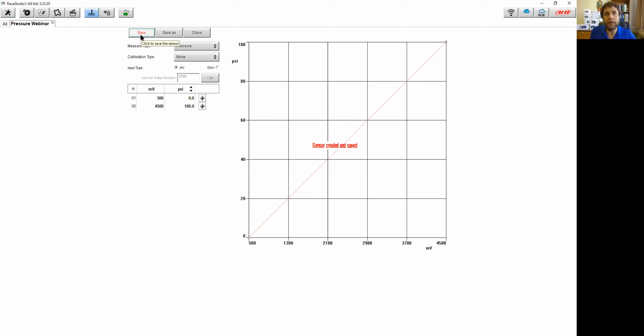So here's a little trick for a lot of people. A brake pressure sensor, 0 to 2000 PSI, is a pretty big range to put in a 5-volt output. And sometimes people will say, hey, my brake pressure at 0 pressure is reading -2 or -5. We used to see that a lot with other manufacturer sensors. AIM has started to make their own sensors that have been, in my experience, really great, and we don't have this 0 problem. But if it's off a little bit, you can go in and change this number and say maybe 491 is the 0.